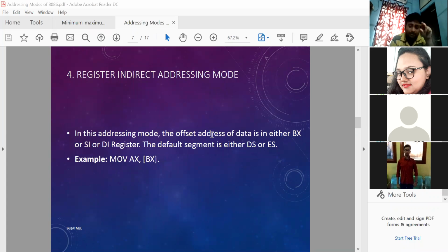What does it mean? The M refers to the memory location pointed to by the HL register pair, that is 1234. From this memory location the data byte will be moved to the accumulator. Clear? So it is indirectly specified. So M-related instructions come under indirect addressing mode.